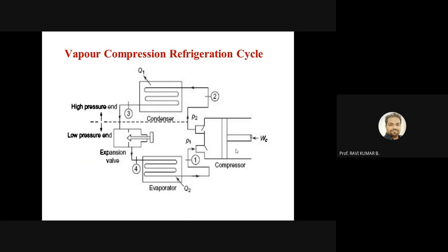If any water droplet comes along with the vapor, it is a wet vapor. In that case, those water particles will stick to the surface and wash away the lubricating oil, which will create a lot of wear and tear, and the function will not be smooth. A lot of vibration issues may be created. Another issue is that they may corrode the surface, with corrosion effects over the cylinder head, so the longevity of the component will be reduced. So our main purpose is always to ensure that the entry to the compressor is a dry saturated vapor.